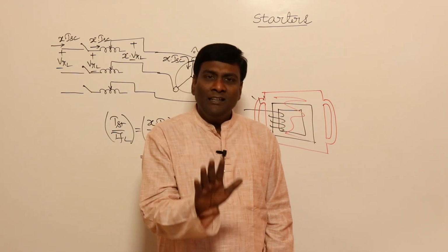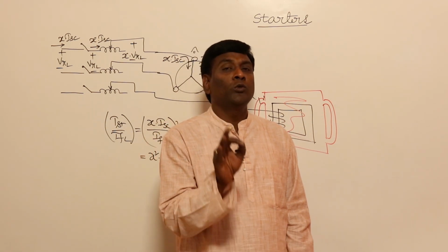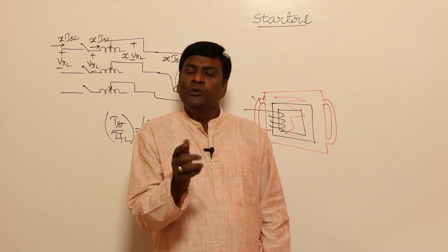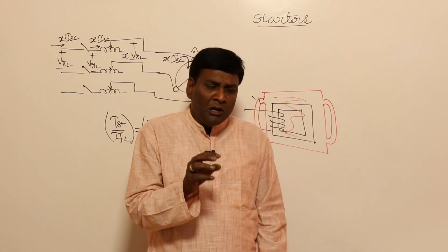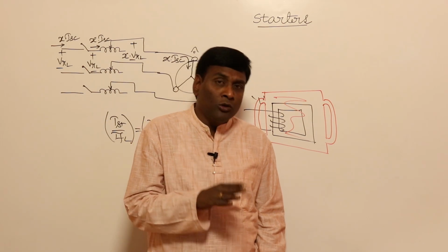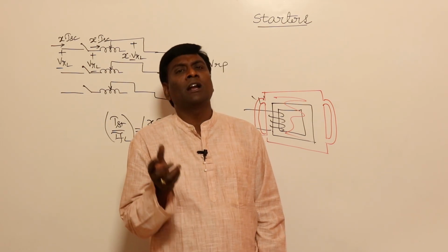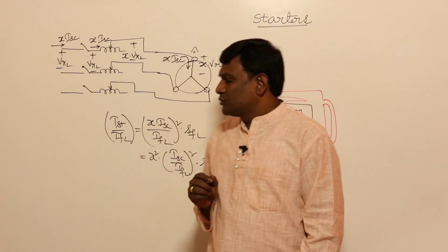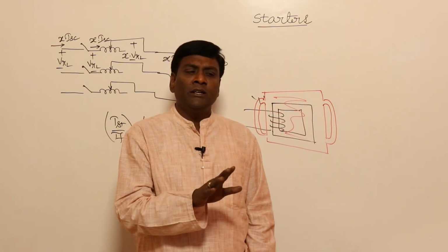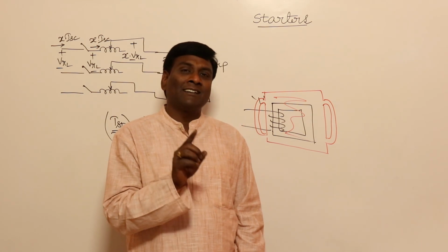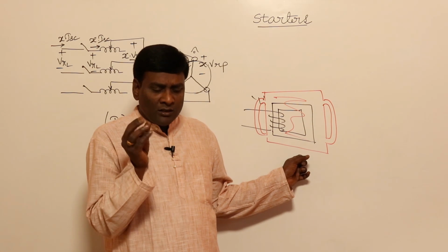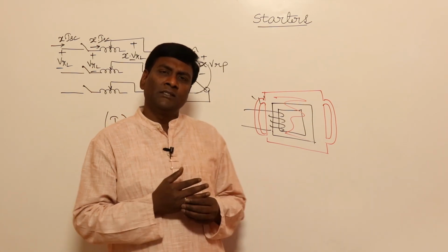So in practical applications, we are going to use only resistor starter. If the duty cycle is less, for example if you have to start the motor and stop the motor multiple times, under those conditions we may think of reactor starter. Under normal practical applications, preferably we don't go with reactor starter. Though it is lossless, its cost is high, because losses occur only in starting, so resistor starter.